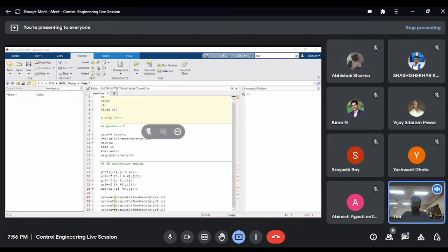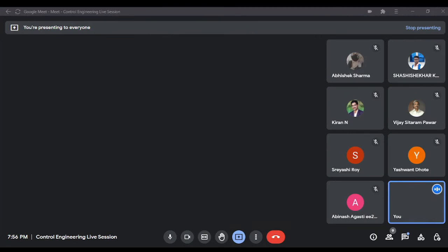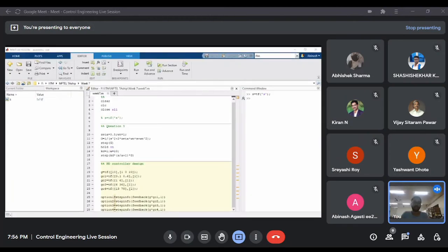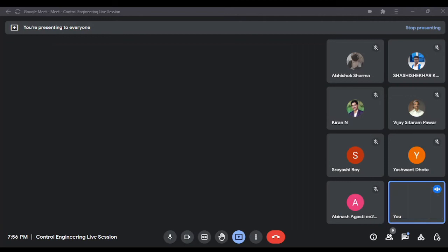Okay, I'll walk you through this. Look at this part from the PD controller design. This function TF gives us a transfer function with numerator given by the polynomial. Can you see my command window? What this does is it initializes S as our transfer function variable S.